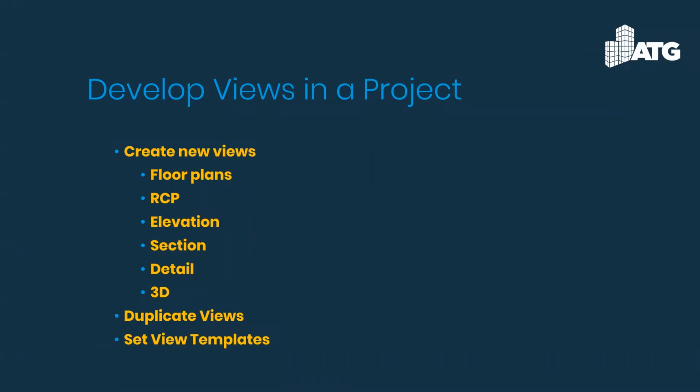Another option that you have, if you have the CTC Express Tools, is a view creator tool that gives you an option to go in and create multiple views at a time. That can be a big time saver over just using the out of the box creation of Revit for the floor plans or reflected ceiling plans. We see this utilized a lot, especially if you have a number of levels for a project. It can very quickly and easily develop those views for you.